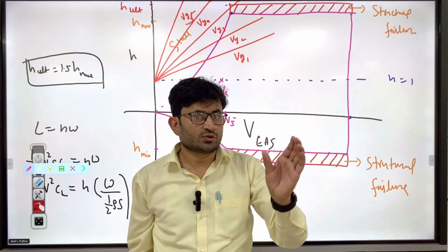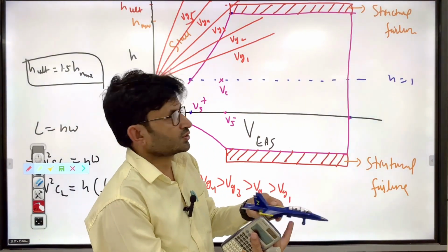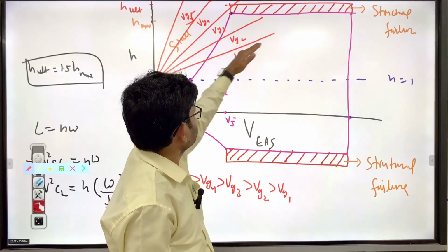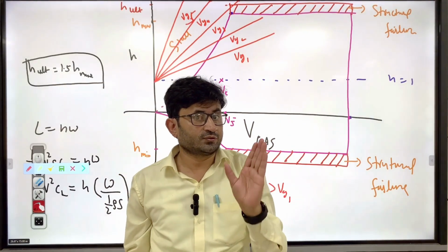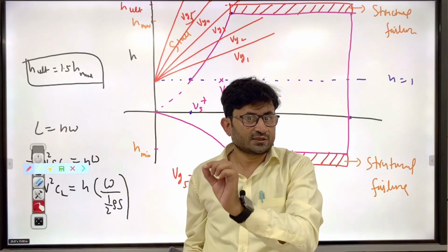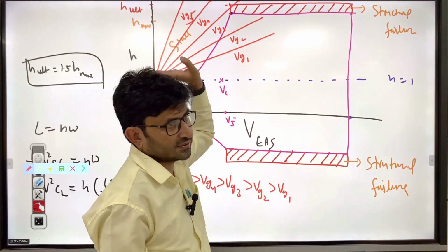will increase. So if a higher amount of gust hits, you have a chance to go out of the envelope. And why am I plotting the straight line? Because I have already shown you that delta n is a function of only V to the power 1, and this is fixed Vg.